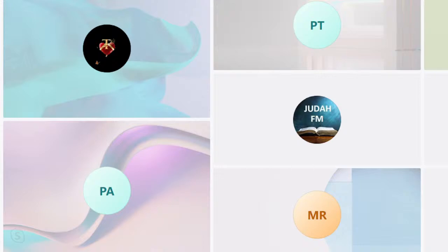Now, there are two different types of LCD monitors that you're going to need to know for the exam, and one of them is called TN. TN stands for Twisted Nematic, and this type of LCD monitor works by liquid crystals actually twisting the light as it comes through. Now, TN is an older and cheaper technology that's been around for several decades. The viewing angles and the color reproduction on a TN monitor are not as good as a more modern LCD monitor. A TN monitor is often used with calculators, digital watches, and older LCD monitors.